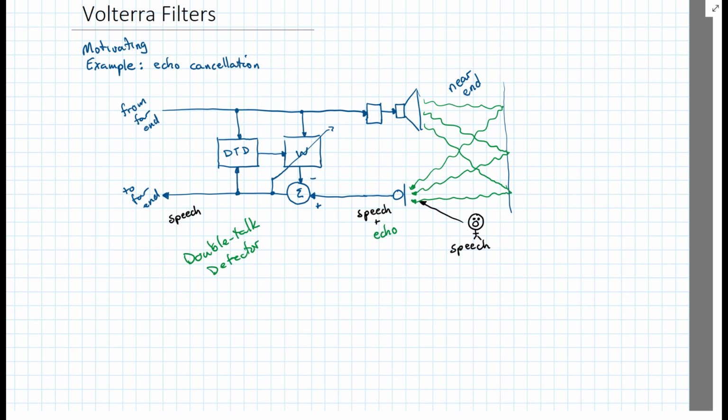However, if it adapts very quickly and there is a significant amount of noise on the desired signal line, which would be this one, then the filter may get some significant misadjustment error. And any misadjustment error is going to cause a problem.